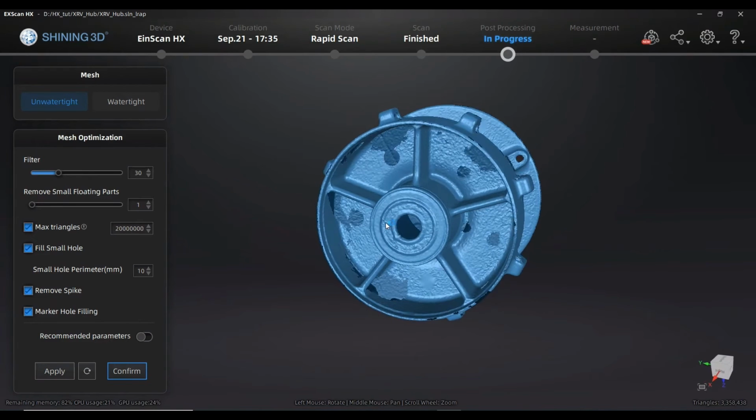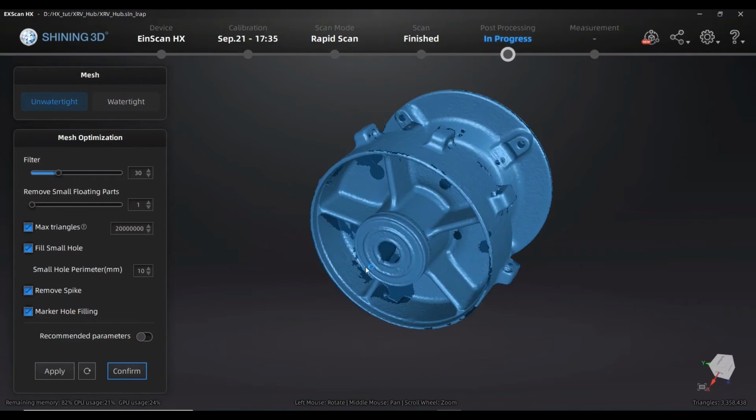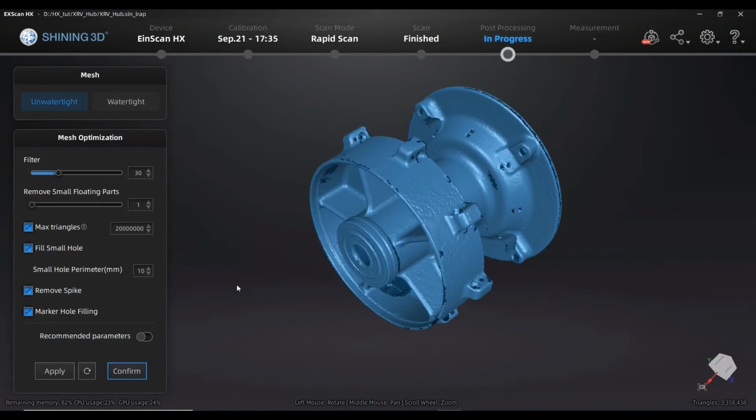I will keep it at a quite high value, because I will show you what is the difference if I don't do it. I don't want to have the size of the model that will be right now created of 3 million triangles and 400 whatever thousand. I just don't want it, but I just show you why I'm not simplifying here over the triangles.